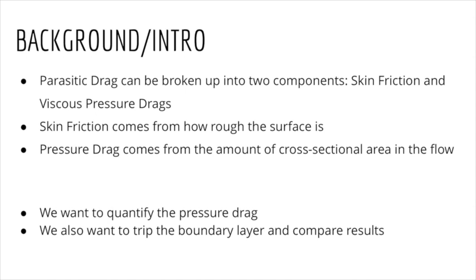The purpose of this experiment is to quantify the effects of the viscous pressure drag. Our team will place a cylinder in the wind tunnel and measure the force of drag at 24 different pressure taps, spaced evenly around the circumference. The Reynolds number and coefficient of drag will be determined for each test run.